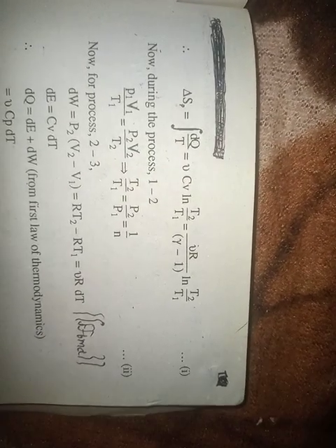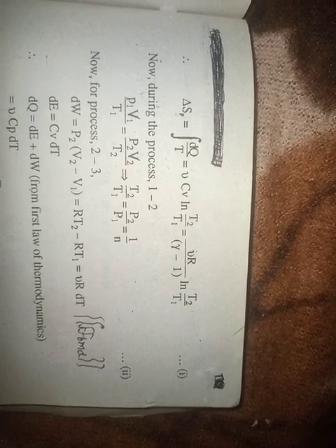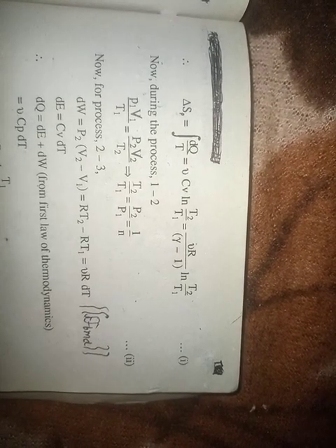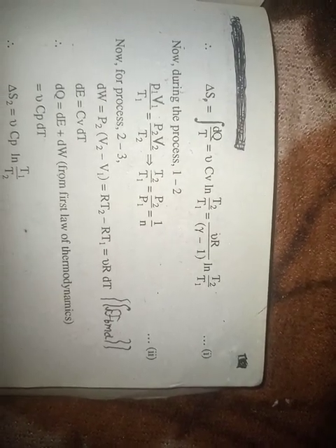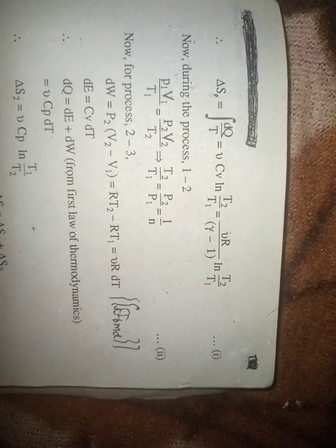Now, during the process 1 to 2, P1 V1 by T1 equals P2 V2 by T2. This implies T2 by T1 equals P2 by P1 equals 1 by N, as V1 equals V2. Equation 2. Now for process 2 to 3, dW equals P2 into bracket V2 minus V1